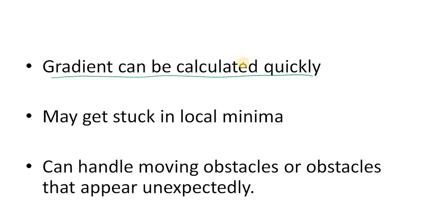Okay, that's why these methods are faster to compute your path, or to avoid the obstacles, or the execution time is faster. So the motion can be calculated in real time, so they can be used for reactive control. Okay, no planning is needed. Just in real time, when you see the obstacle, you just try to avoid it, and so there is no planning needed in advance.